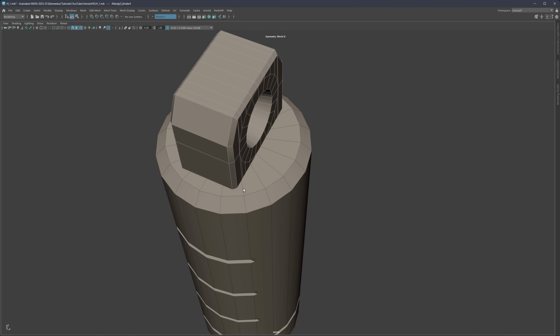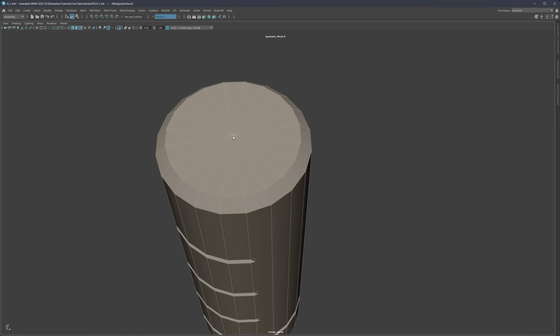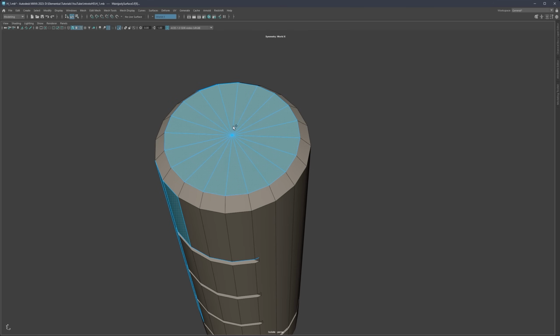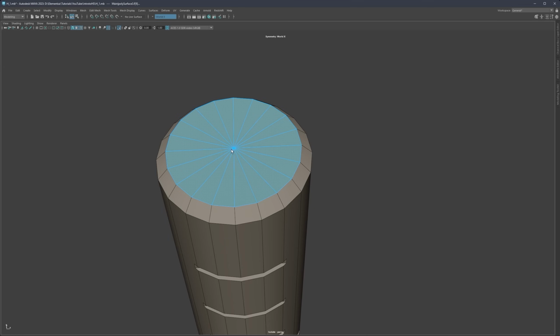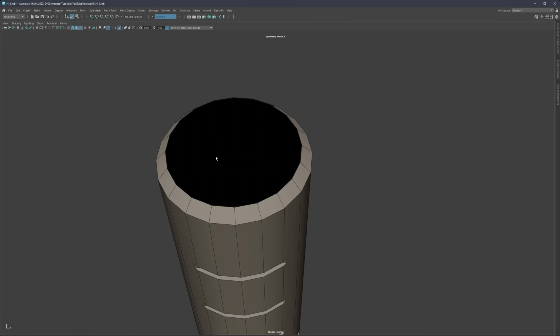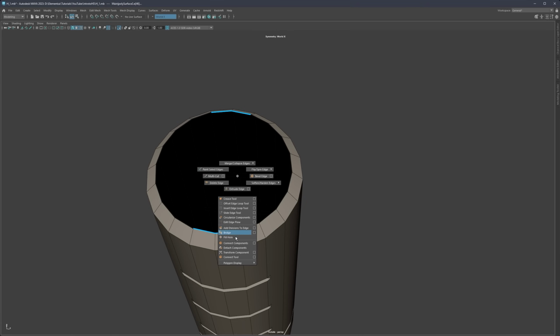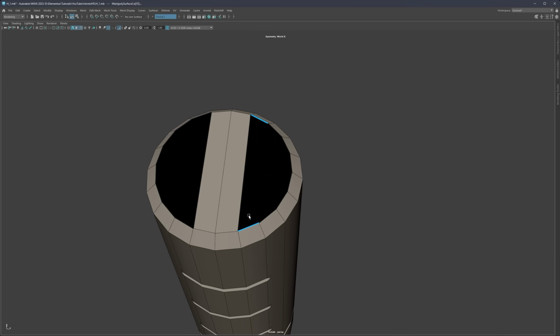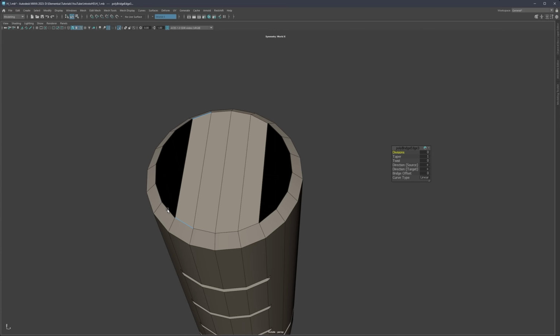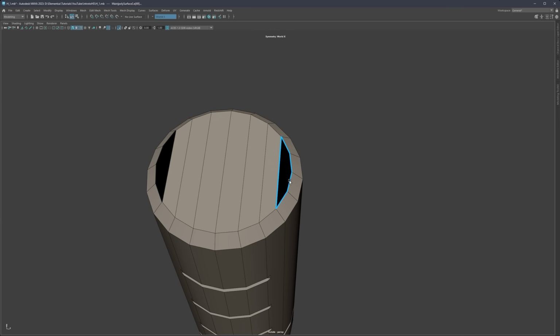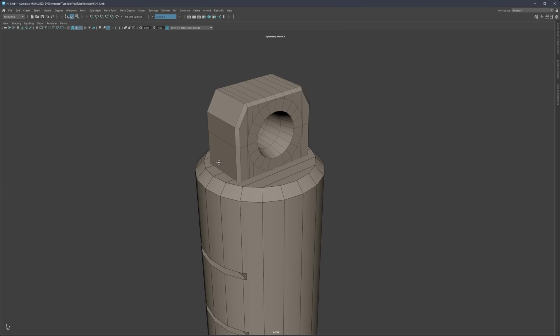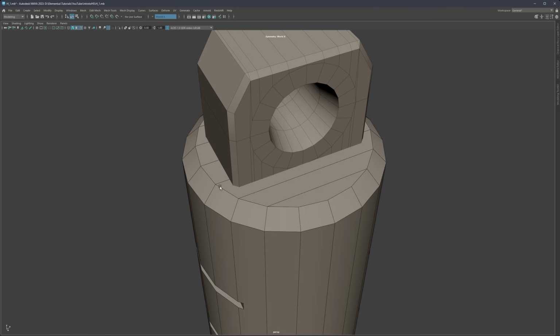In addition to that, it also means that this top right here, if I Control-1 to isolate it, this part from the top, let me also turn camera-based selection on, cannot be like this. We're going to need to have a different type of topology, which is going to be something along these terms. So let's select these two and let's bridge this together by holding G, G, G, and G. And then here, G as well, G as well. So just repeating the operation. So we're gonna need something like this instead, where we can actually connect everything in a straight line.